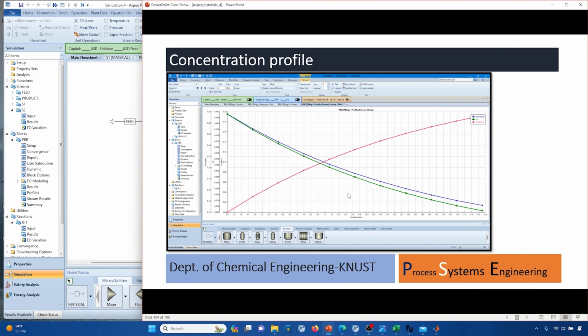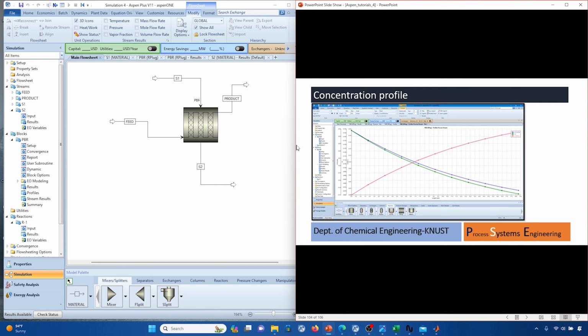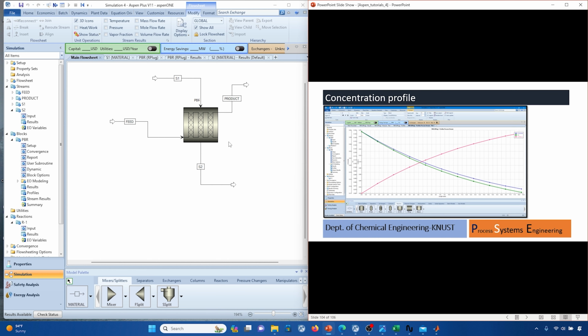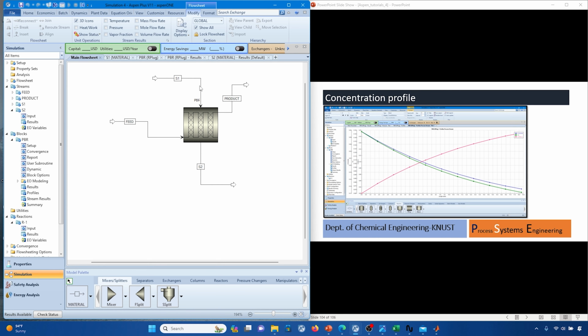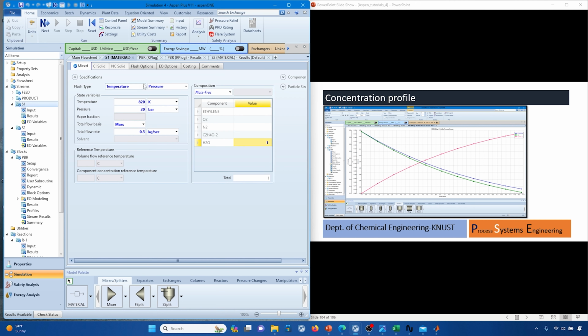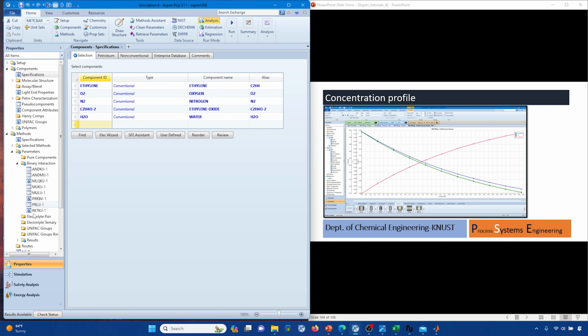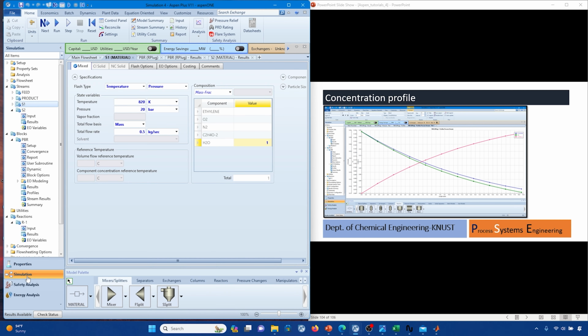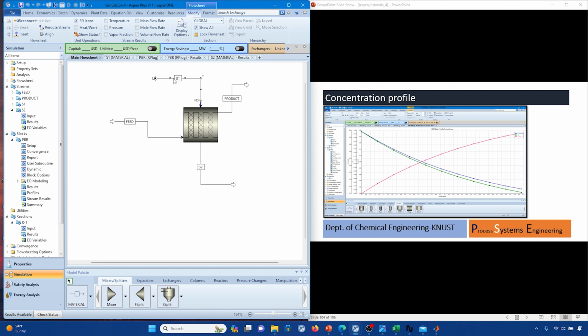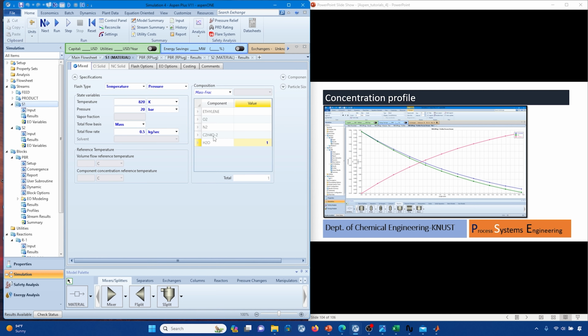As I was saying earlier, you could decide to run with the specification of your cooling or heat by adding the utility stream. It's the process stream. So in this case, I could decide to use water. So adding water to my components here, add water, and then come here. If water is my coolant, let's add that stream, the input and output, and specify the parameters for my water.